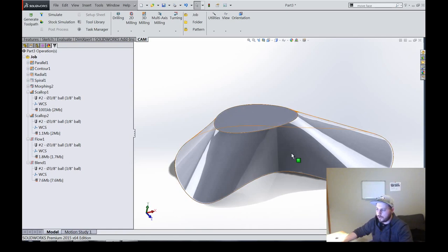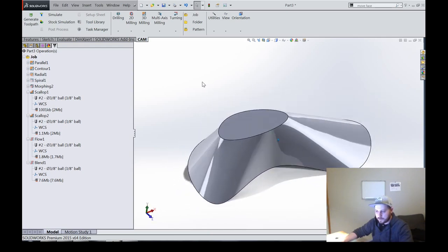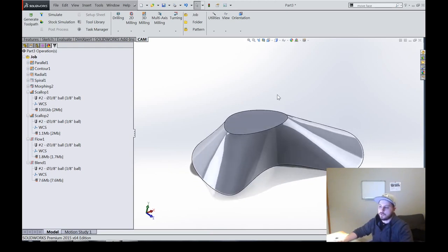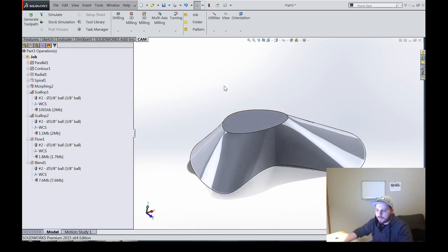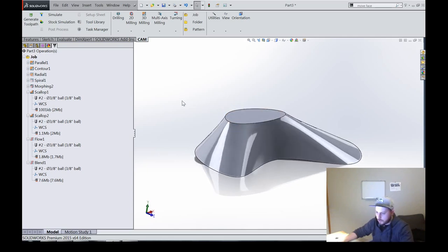There's some stuff you can do. SolidWorks kind of lacks the tools to do this, but you can pull the surface out, use different software to realign and correct the UV spacing and direction and all that stuff, and then bring it back in. But if you're dealing with anybody that cares about their surfaces, once you do that, you've kind of destroyed the integrity of the surface. You're no longer really working with the same surface, and the likelihood that it looks the same under evaluation or that the reflections are right is pretty small. So I'd really refrain from doing that. But anyway, that's the issue.